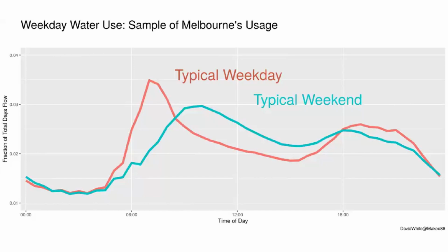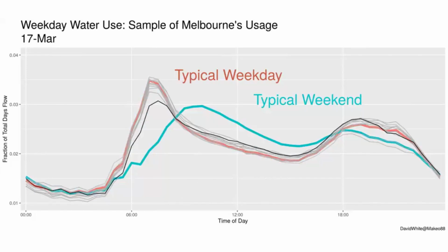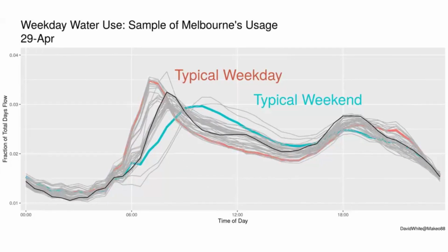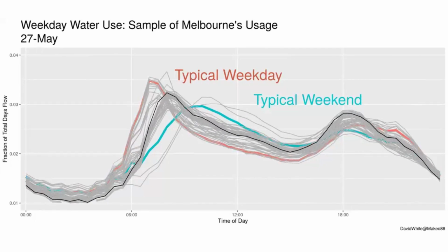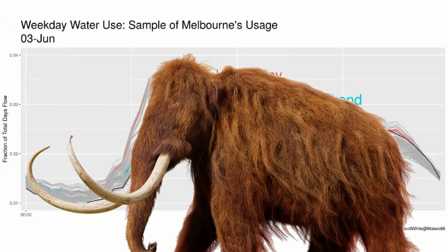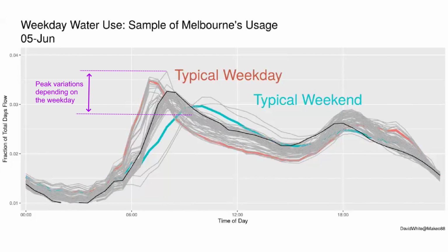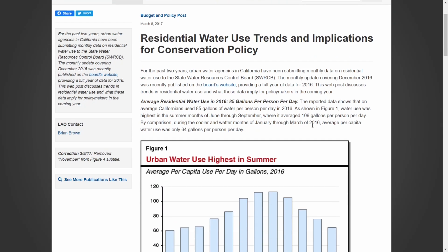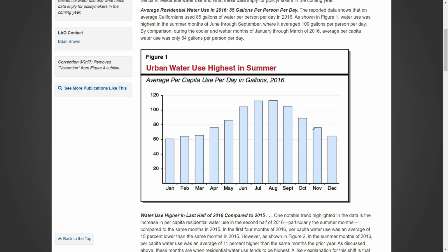But this daily peak factor is not the only one at play. There are also variations between the days of the week, with weekends usually having lower consumptions. These variations are taken into account with a weekly coefficient. Finally, there will be a seasonal pattern with more consumption in the summer months and less throughout the winter.